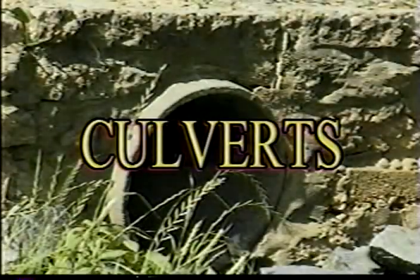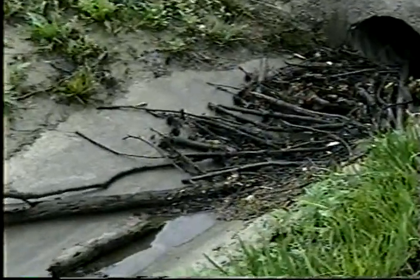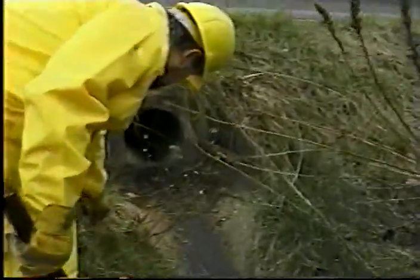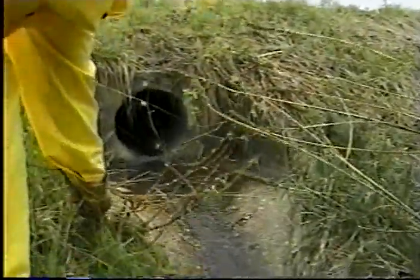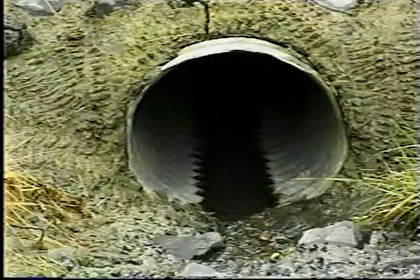Culverts must be kept free of obstructions. Sand or sediment deposits should be removed as soon as possible. During storms, critical areas should be patrolled and inlets kept free of debris. Inlet and outlet channels should be kept in alignment, and vegetation should be controlled to prevent significant restriction of flow.